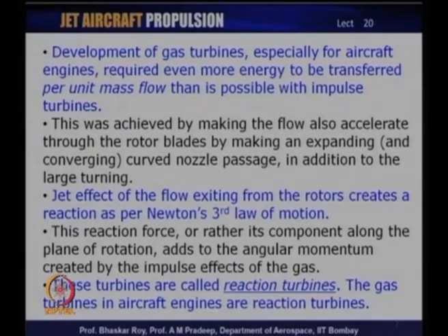And these turbines hence are called reaction turbines, and all gas turbines in aircraft engines are indeed reaction turbines, because we desperately need these turbines to create a lot of work per unit mass flow, and that is why we need to have reaction turbines. Just impulse turbines would not do. We need to have more work done out of these turbines to meet the requirements of a compact and lightweight gas turbine inside an aircraft.